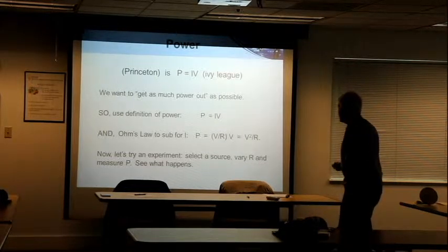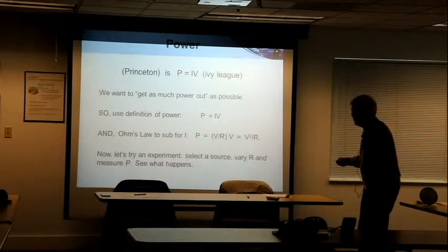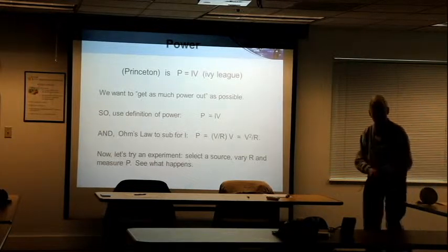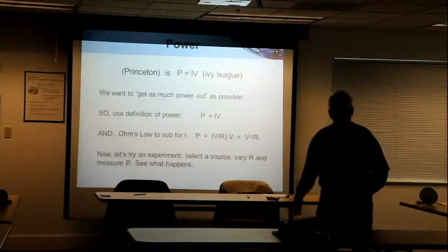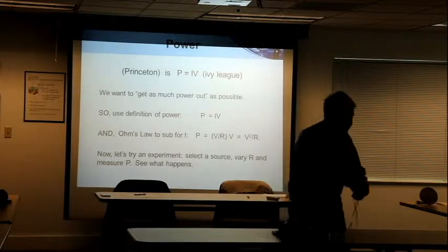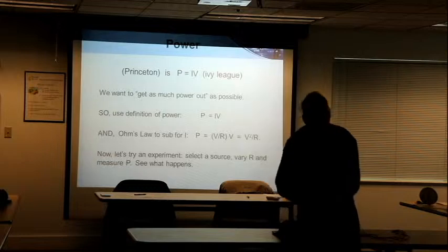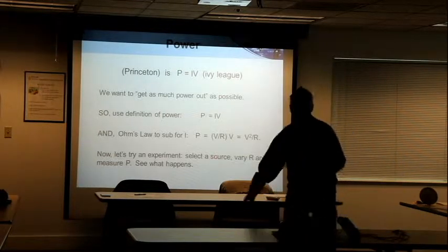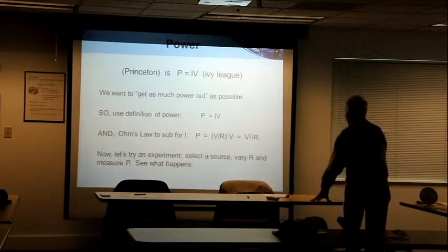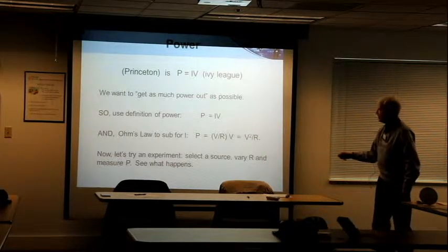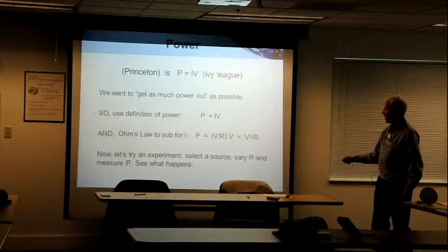So if we have the definition of power, I want to express that power in terms of just one of these variables. It's easier for us to measure voltage today. I'm going to ask Henry, KH6VM, to help me with these measurements today on our little gadget. If we can just measure one of these things, either I or V, it's handy to measure the voltage only and then use Ohm's law to replace I with V over R. See how I've done this in the third line?